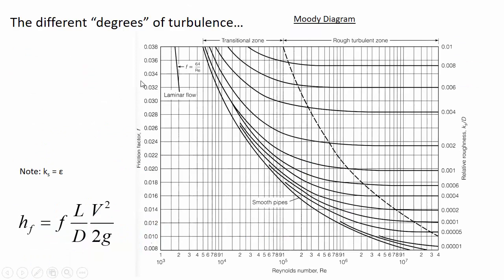Now, first, the easy thing. If you have laminar flow conditions, what this diagram and the formula that accompanies it show is that you can estimate the F value, the Darcy-Weisbach friction factor, as just 64 divided by the Reynolds number. So that's a really easy formula, but the problem is that flow is hardly ever laminar. So you won't really ever calculate the F value with this formula.